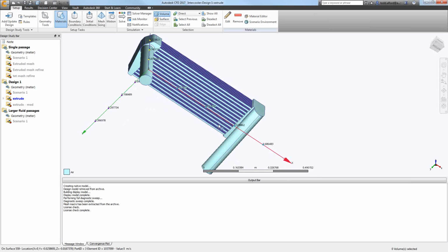The one thing that I did change out of the solver parameters, I used ADV5 because I wanted to be better about the pressure drop, realizing that that's probably a design constraint. If you can make the pressure drop lower, most of that is going to depend on the flow through the channels anyway. So if you're changing those channels, you'll get a better pressure drop, a higher flow rate, all of that stuff.